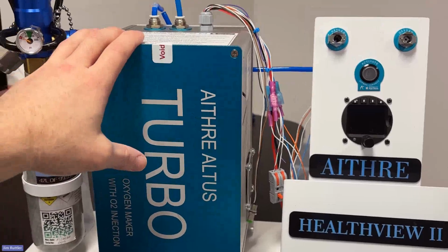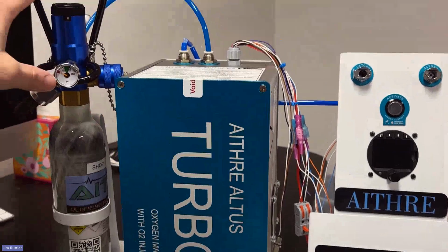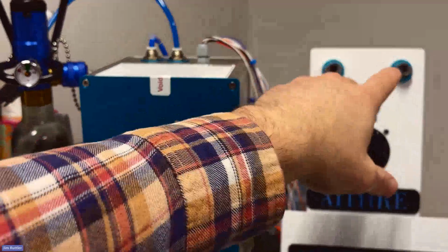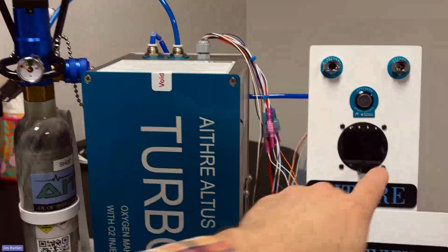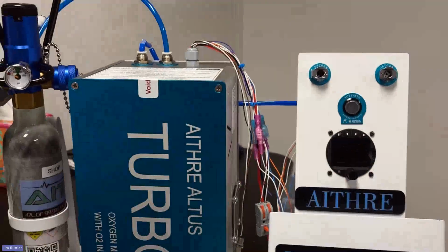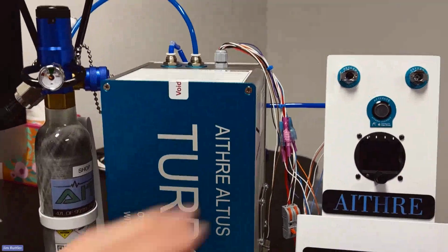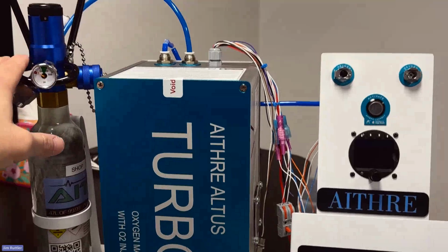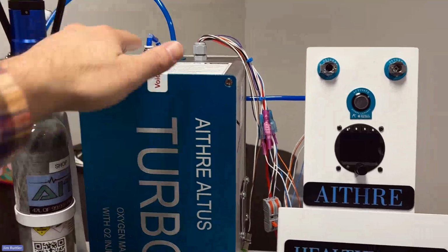If you go above 18,000 feet, the oxygen from the bottle kicks in and begins to enhance the flow rate into the cannula ports. Now it happens automatically, and you can monitor it with the health view. There's no need to switch cannula ports between the maker and the bottle. It automatically blends it in the common output.